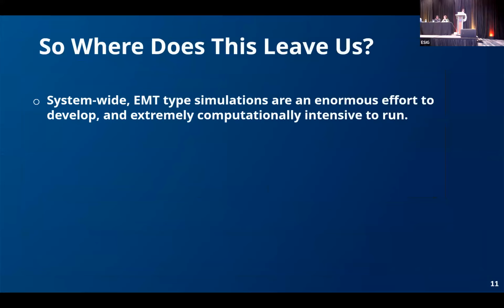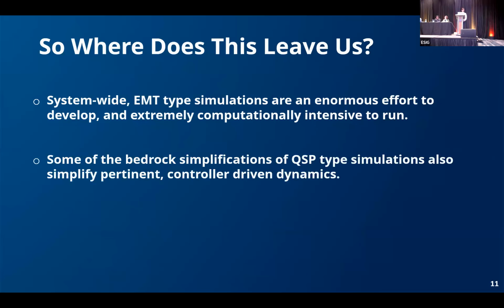System-wide EMT type simulations are an enormous effort to develop and extremely computationally intensive to run. That goes without saying. The Maui system is not a big system, 200 megawatts. The Western Interconnection is about a 200 gigawatt system, so that's 3 orders of magnitude larger. But some of the bedrock simplifications that are inherent to QSP type simulations are also simplifying pertinent controller-driven dynamics.